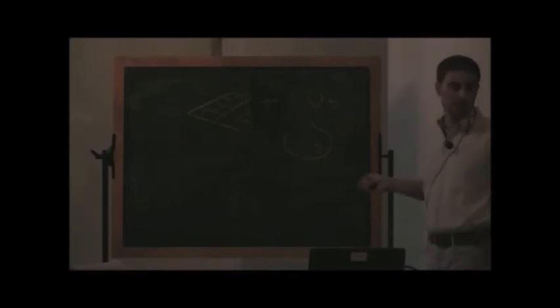So when you want to homogenize this plate as a thick plate, you first compute the thin plate constitutive equation, the bending constitutive equation, and I will present what happens inside the RVE. So inside the RVE, you have two beams for each direction. And obviously, those beams have their own resultants along the line, namely the resultant, a bending moment and torque. So longitudinal force, shear forces, two bending moments, and a torque. A torsion. Sorry, I'm always mixing.